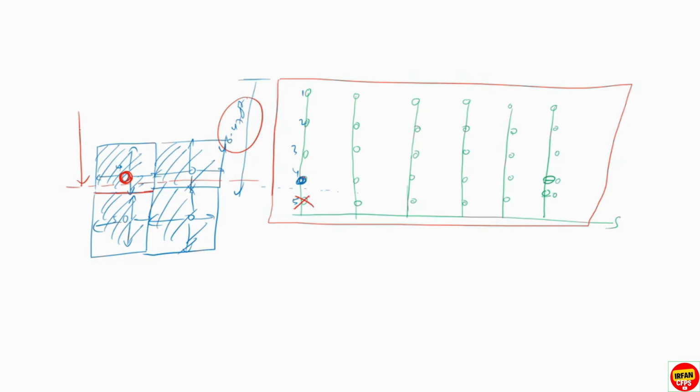We'll not consider the 5th sprinkler. But if your 46.47 feet is coming here, it means it crossed the 4th sprinkler and arrived into the 5th sprinkler's coverage. So it means we need to consider the 5th sprinkler as well. Otherwise, no need to consider the 5th sprinkler.